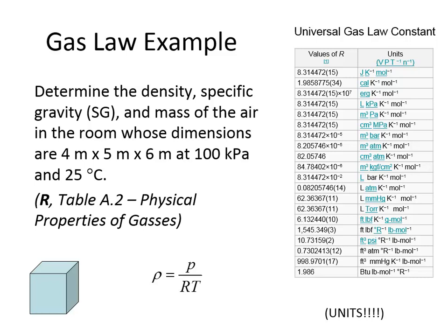In the book it says gamma. Should we use like that, or does it just specific gravity? It can be the ratio of densities or the ratio of gammas. So it could be gamma of air relative to gamma of water. And that's also another definition of specific gravity. I think it says as much in one of our earlier slides, that it's the ratio of either. Because gamma is simply it's G times the density. And so if G is in both the numerator and the denominator, then it cancels out. So both work. Other questions from this example?